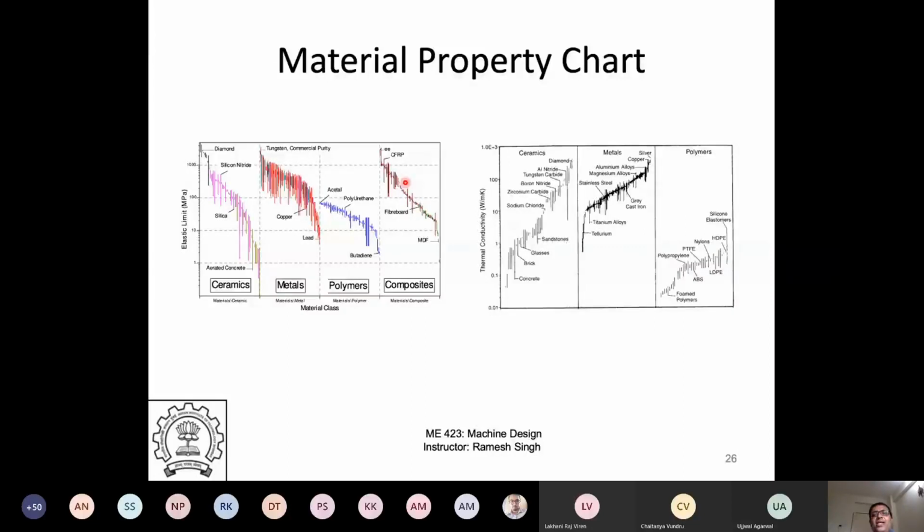But then composites have a lot of advantages. They have very high toughness. They can take a lot of energy, and they can also have engineered strength in any direction you want. So if my loading is in a certain direction, I can actually create large strength in the direction of loading, which is not easy to do in any other process.